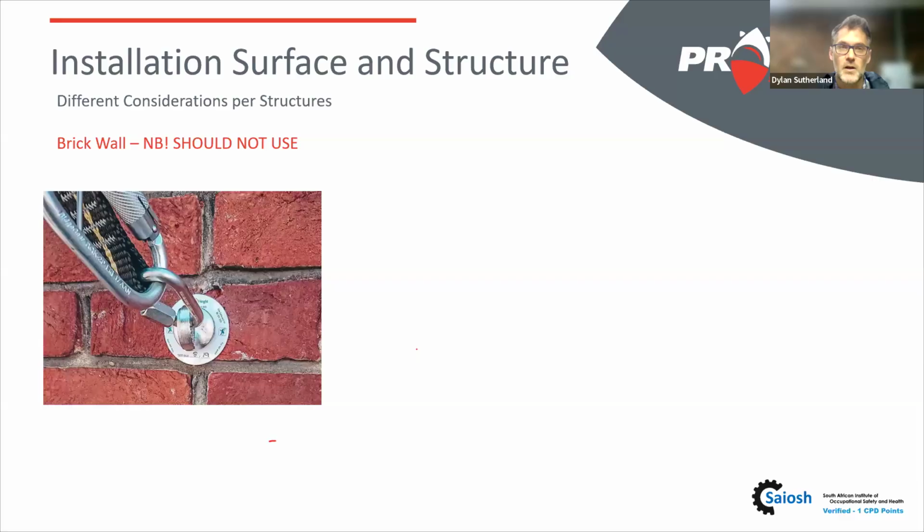The other thing about bricks is bricks have holes. They've got 2 or 3 holes in them. Once again, it's not a solid structure that's going to arrest the fall. The third point is the grouting, or the adhesive that's being used to stick these bricks together, basically. What strength does it carry? There's no certification for fall arrest in that, I can promise you. It's just designed to stick bricks to bricks.